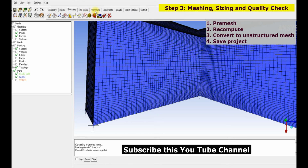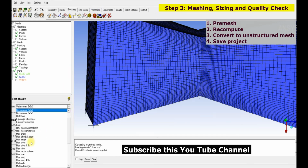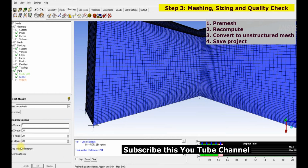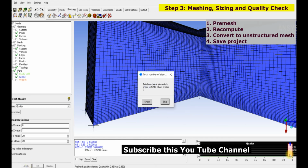Then the next option is we can also check the mesh. Here the option is check mesh. Here you can check the aspect ratio. Here the maximum aspect ratio is 5. You can also check the angle, skewness, distortion, mesh quality. Here you can also check the quality if you want. This mesh quality is okay, 0.95.